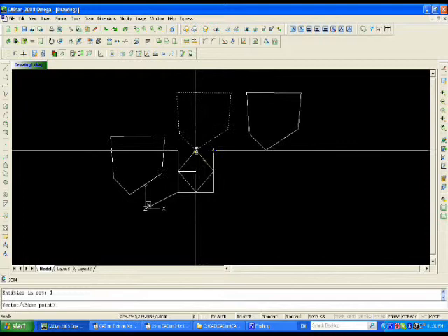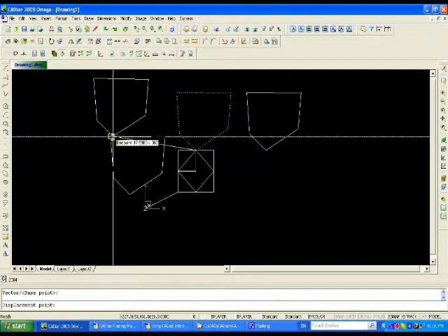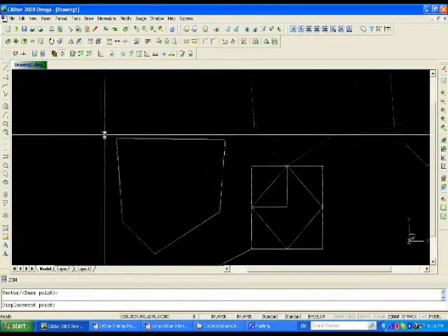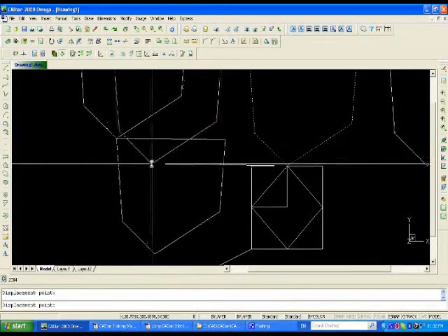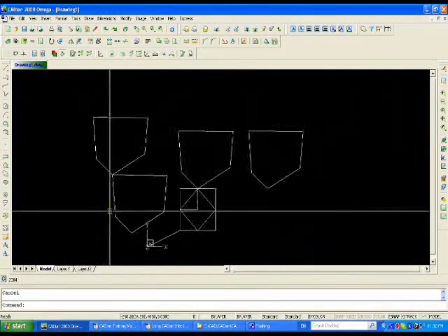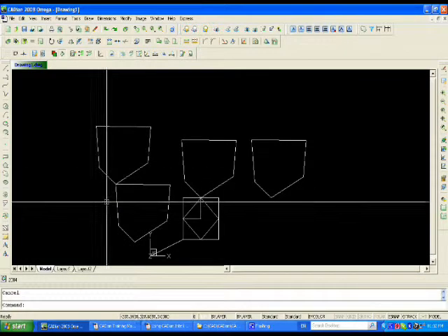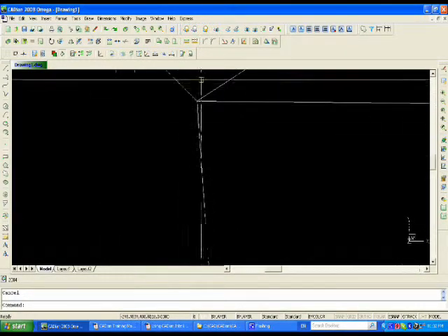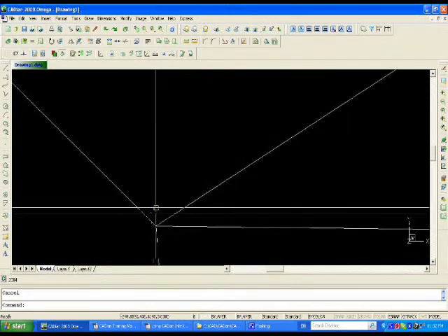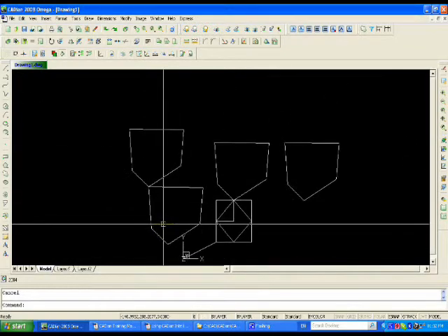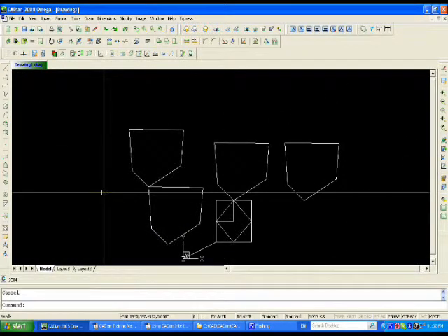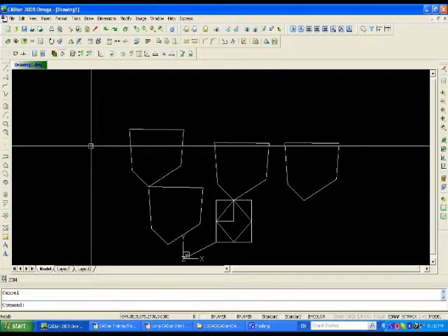Now be careful, it's snapping to the midpoint, that's fine. But what happened here just now, it wasn't quite going to the end point. So I need to make sure it's going to snap to the end point. That's something you've got to be very careful of in the 2D environment, in the AutoCAD type thing, that you actually do go to the point you intended. And we see that a lot in AutoCAD drawings, that somebody says it doesn't quite work, but the lines don't join at the ends. And that can create big problems for you in the AutoCAD type of DWG environment.